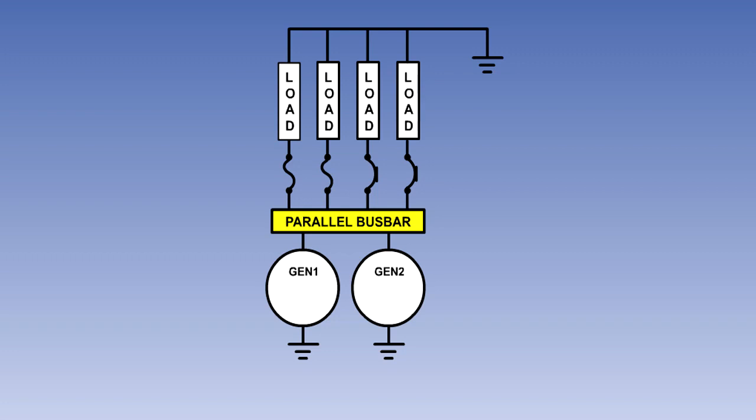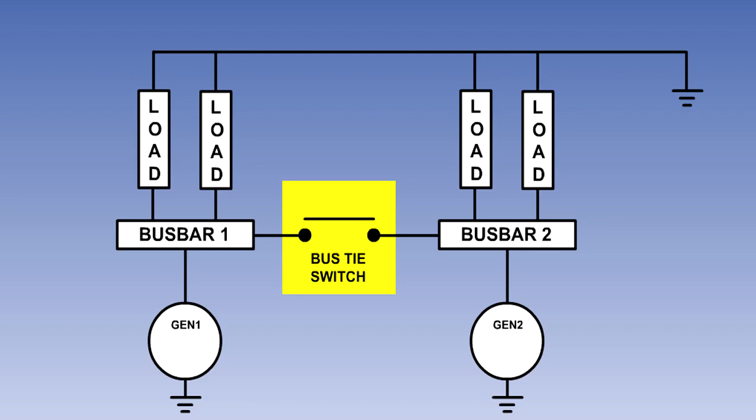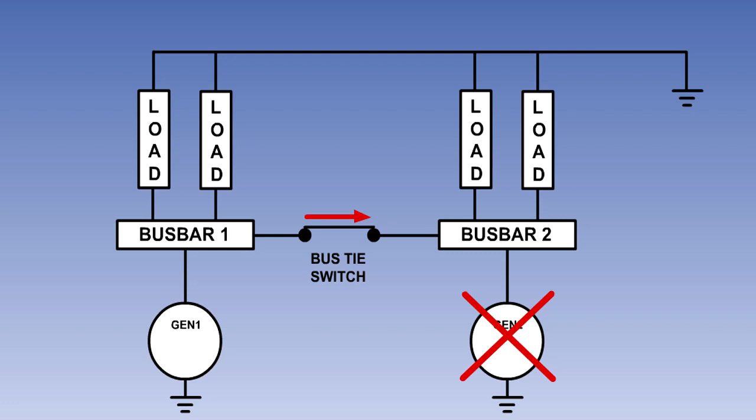In order to ensure the continuity of supply, generators or alternators can be operated in parallel. Or switching systems can be incorporated to ensure that the loads of a failed generator or alternator are taken by a serviceable unit. Failed generators can be isolated from the distribution system.